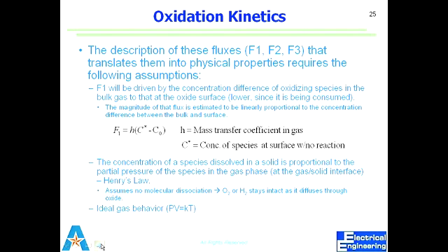So, by changing the gas species in the furnace, I can control my oxidation. I can use nitrogen to reduce the fraction of oxygen in the furnace. Why do we want to do that? Why would I want to dilute my concentration of oxygen in the furnace? To control the process, to get to very thin oxide. And why do you want thinner oxide? Because of device scaling.